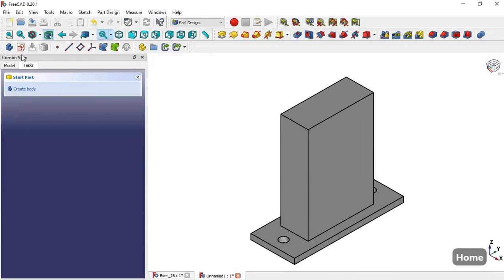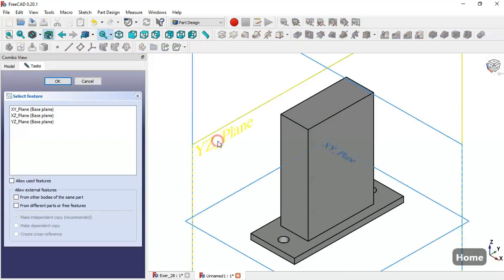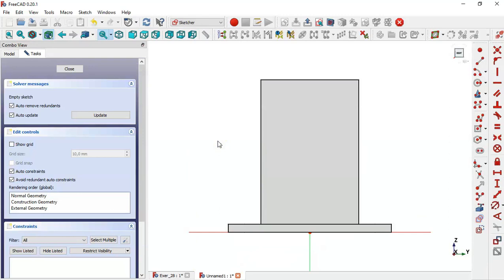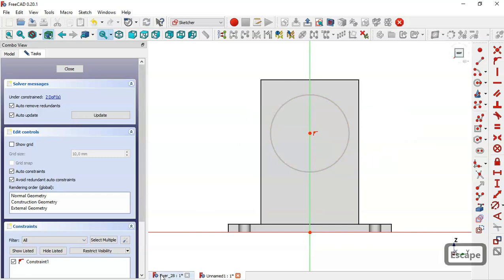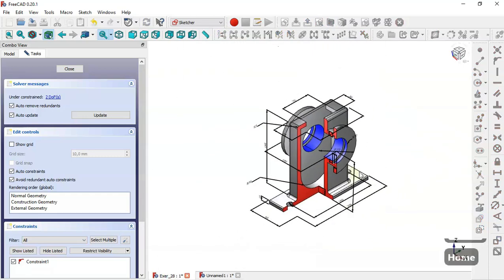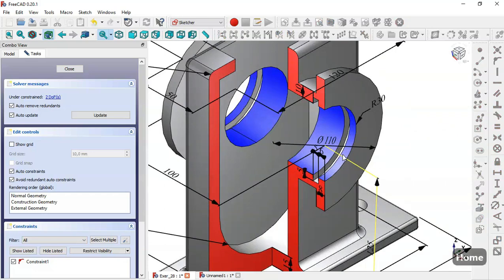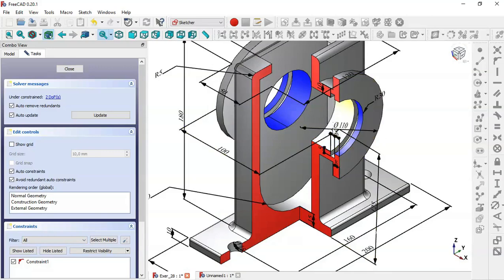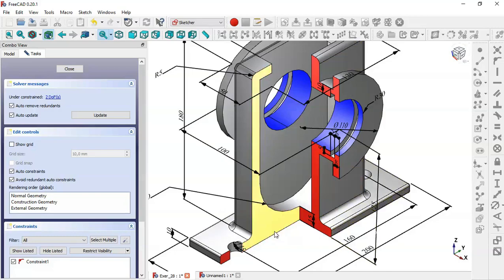Okay, next create a new sketch in the YZ plane. And here switch to section view, select the circle tool and draw the circle here. And now let's see the dimension for this circle. So here we have this radius here for this wall and we have this dimension 10. Okay, the distance between the center of this circle to this point here is 125.